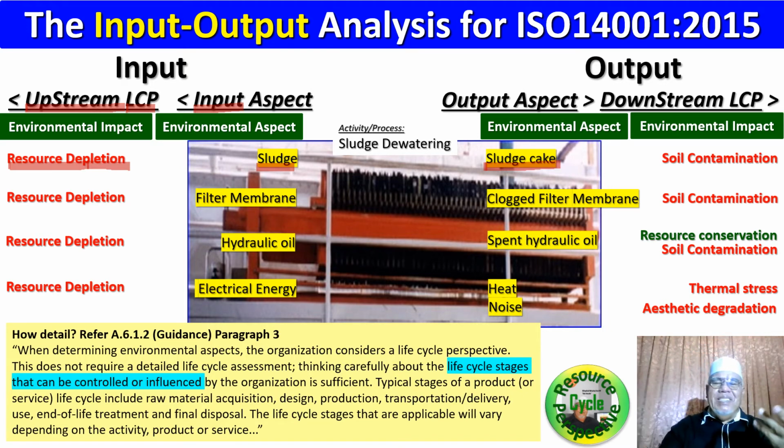But in practice you can have some slimy sludge cake, and sometimes the cake won't fall down from the filter membrane and you have to do raking. Those are due to excess use of coagulant and flocculant. That's another story. You can consult your wastewater treatment plant consultant and your trainer and your 14001 EMS consultant, all right? Get their expert opinion.